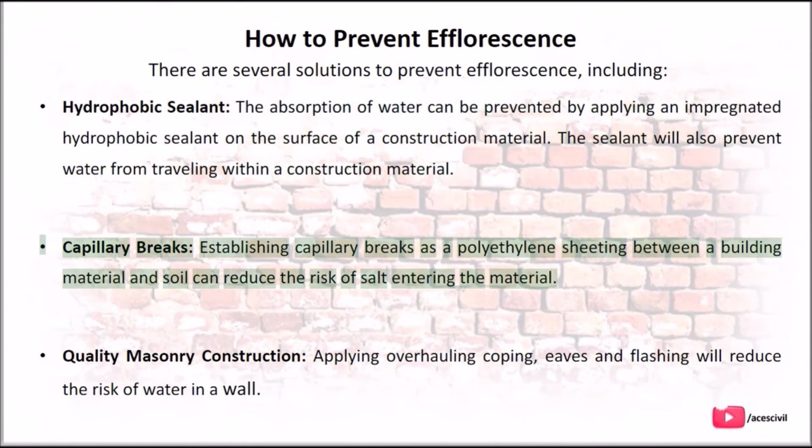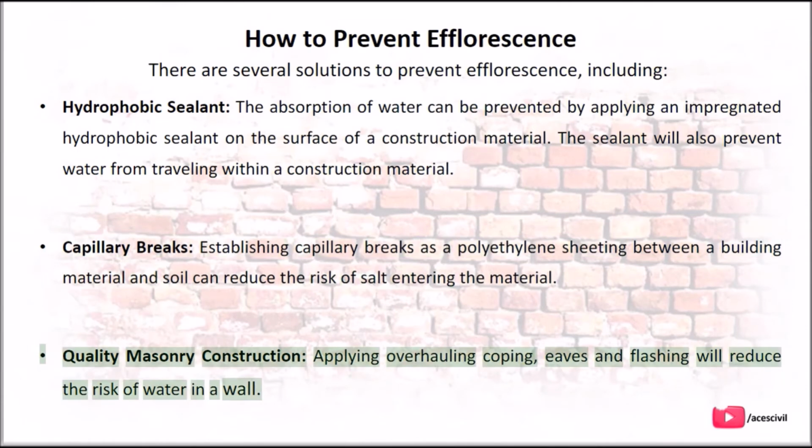Capillary breaks. Establishing capillary breaks such as polyethylene sheeting between a building material and soil can reduce the risk of salt entering the material. Quality masonry construction. Applying overhanging coping, eaves and flashing will reduce the risk of water in a wall.